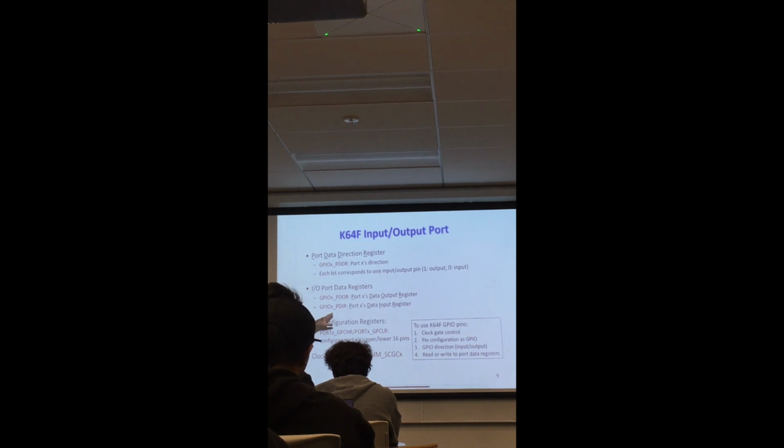The same thing is in ATmega. In the 9S12 microcontroller that we used before in this class, actually it was a single register for both input and output. So when you switch over to another microcontroller, you have to check: will you use the same register for both things, or for input and output, do you use different registers? ATmega and ARM microcontrollers use separate, different registers.